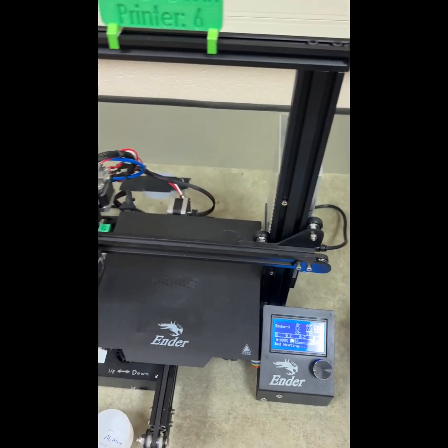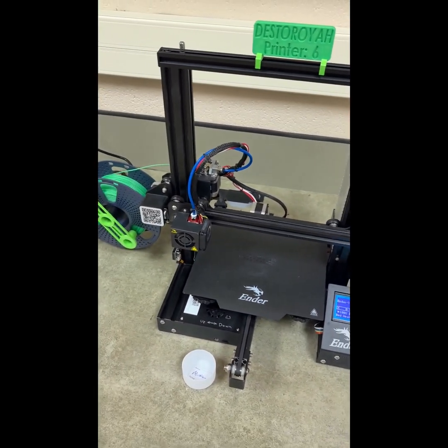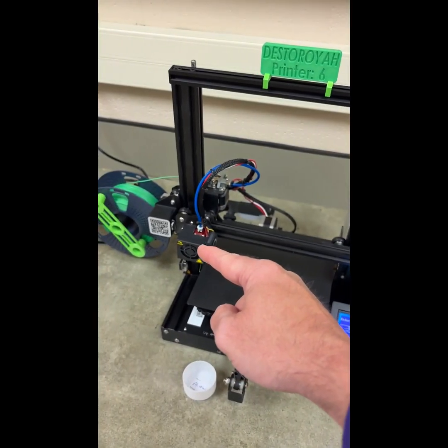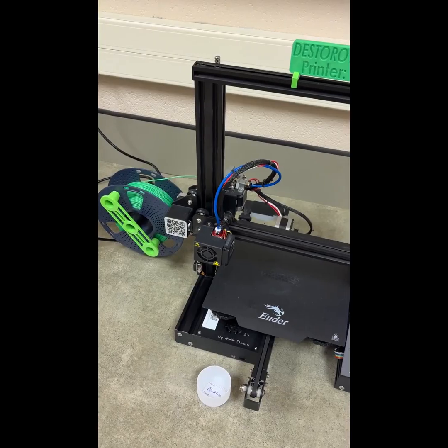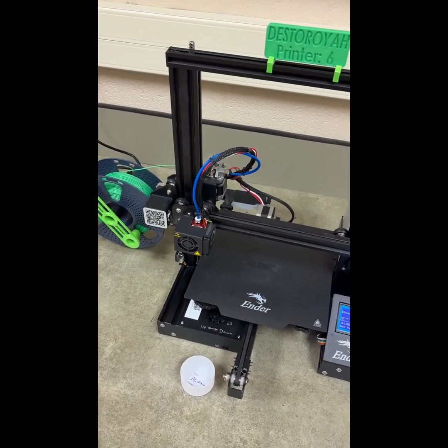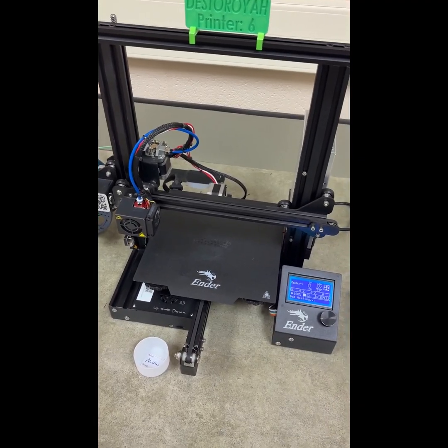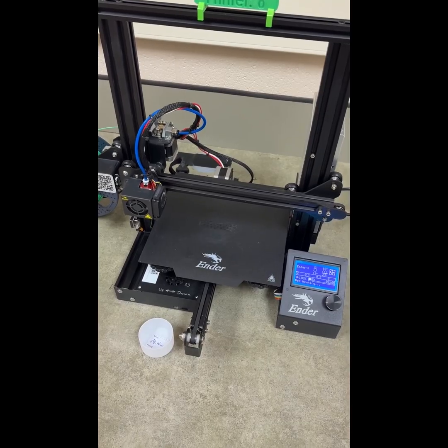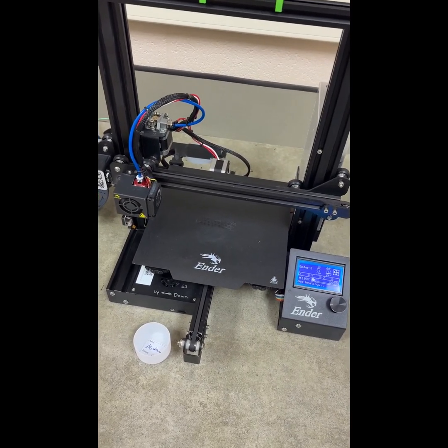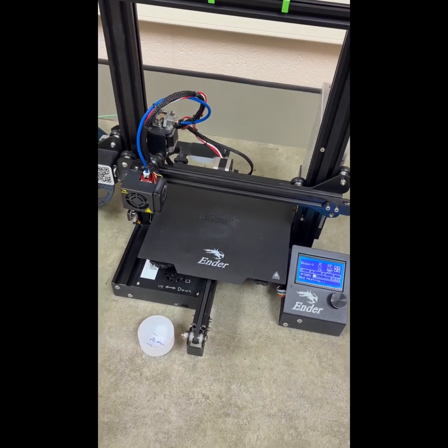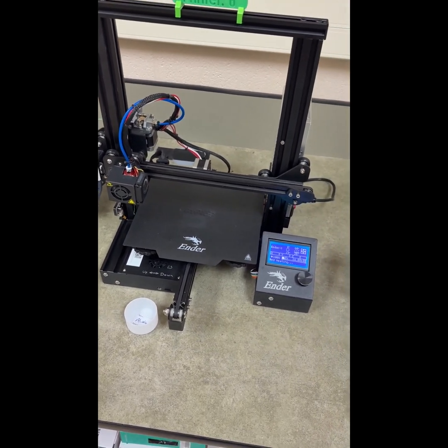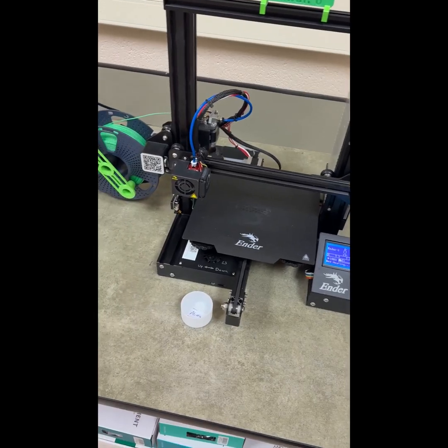And that's it. The machine will warm up. The nozzle's underneath here. It'll heat up to about 200 degrees Celsius, which is about 385 degrees Fahrenheit. And the platform will heat up to about 60 degrees Celsius. And don't ask me what that conversion is into Fahrenheit either. But now that we've set it, now we can forget it.